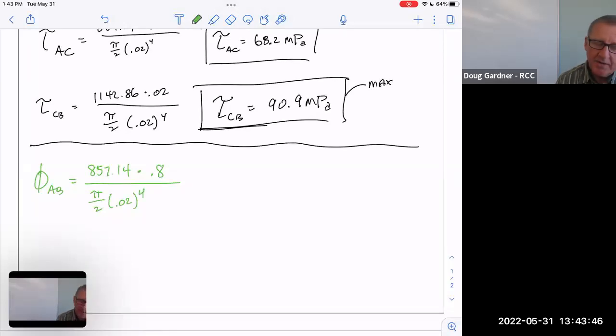And notice I'm thinking meters. Everything here is meters, Newton meters, and so forth. So I'm being lazy, but I know it's going to work. And then this was 75 times 10 to the 9th pascals, which is newtons per square meter. Again, it's a good exercise. Twist should come out unitless because it's a radian measurement. So I should end up with nothings if I stuck all those units in there.